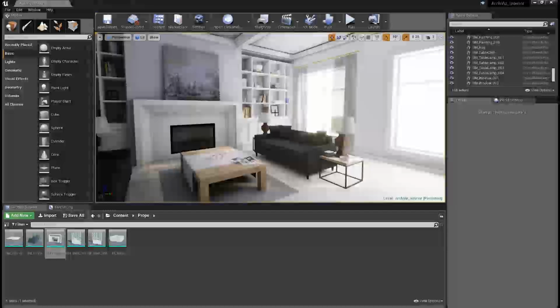By making it a longer distance further away from the camera lens, it can actually improve the Z-fighting issues in scenes that are really large, exterior scenes and whatnot. The only problem is you don't have access to the far clip plane in Unreal, which means that adjusting the near clip plane may not have much of an effect because generally you want to adjust these two together. They work in tandem. But I'll show you where you can actually tweak it.